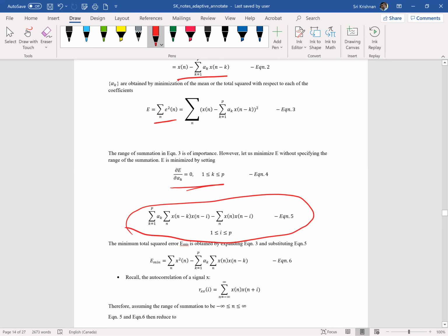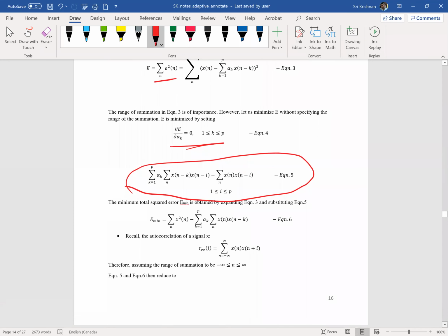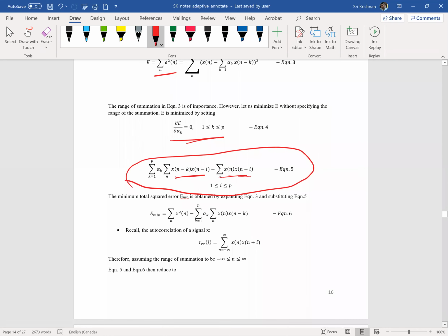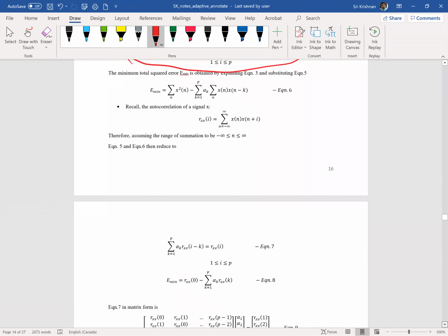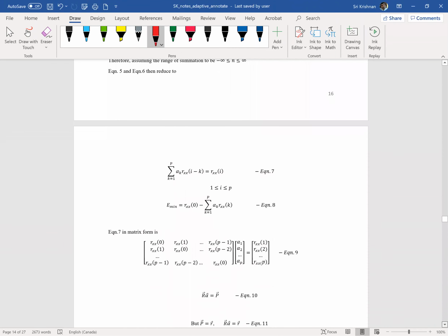And if you look very closely into this expression, you will realize the terms are now starting to look familiar. This term, for example, is nothing but the autocorrelation value of the signal. Again, this term, because we have the desired response to be the signal itself, is also an autocorrelation term. Now, just by substituting them with autocorrelation terms, we have P of those, and as we indicated in the adaptive filter design problem before, we could put that into a matrix notation like this.